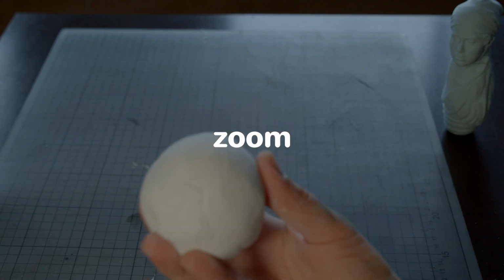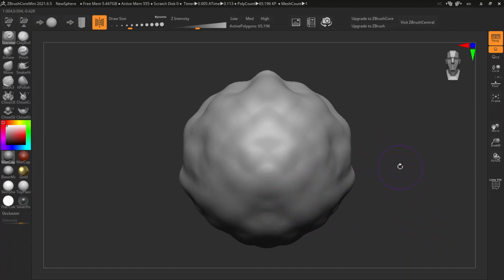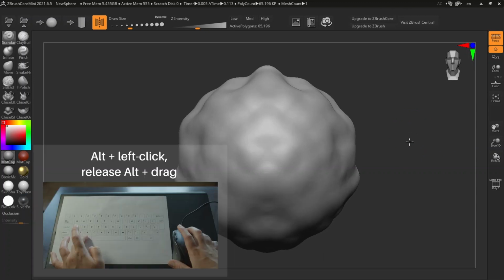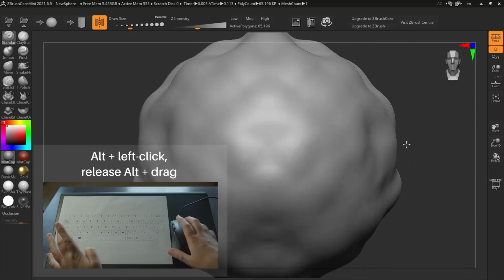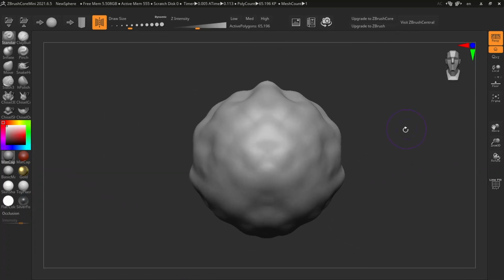So Andrea, you can also zoom to the object by pushing the Alt key and your left button on the mouse. While doing that, you leave the Alt key out and start to move your mouse back and forth, so you can zoom. Or otherwise, you use the button on the right of the user interface. You just push Zoom 3D and keep holding the left click of the mouse and go up and down.